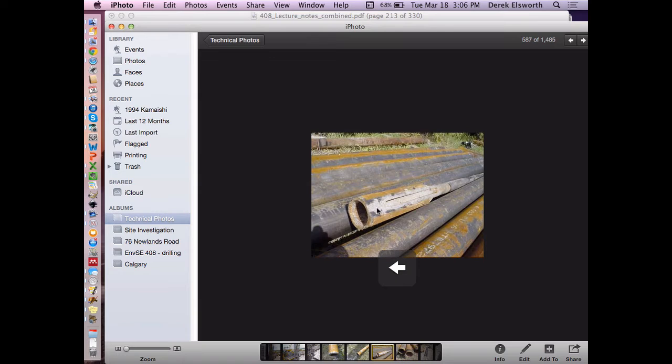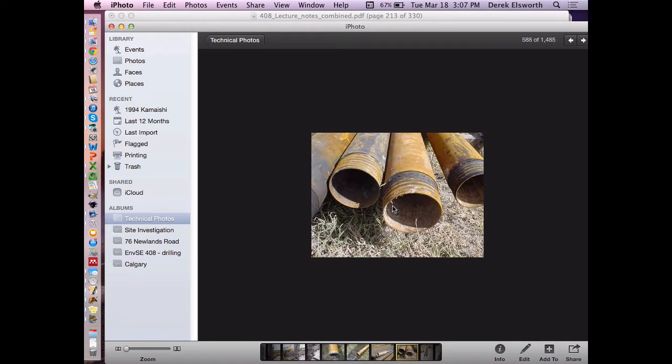And then when you want to retrieve it, you send down this fishing tool. So this fishing tool goes down 100 feet down to the bottom. You can see that these are little spring-loaded clips on the side, and the core holder has a little conical clip on the top that has an undercut, and this just clocks on this and the ratchet catches it. It releases the thing from the drilling cutting shoe, and then it physically, on a piece of steel cable, carries this all the way up to the top of the hole. So this is the fishing tool that takes the wire line.